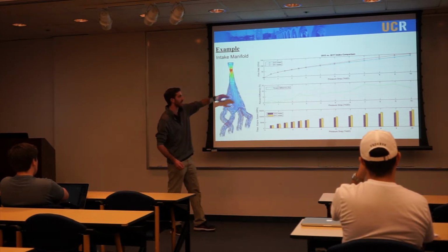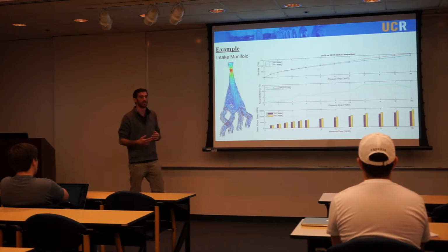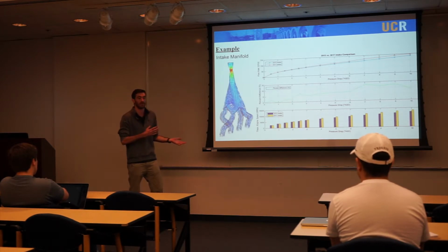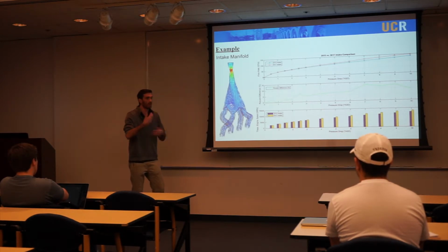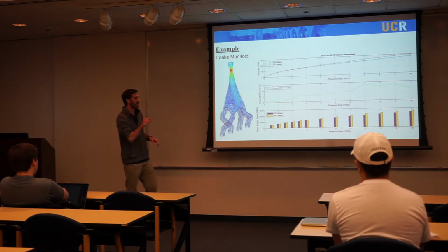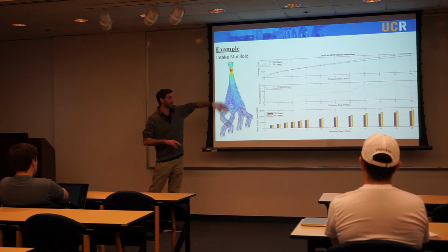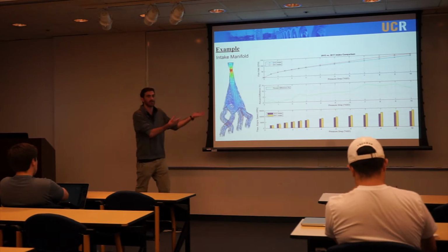So testing both the intakes and getting the pressure drop difference between them and seeing if you're improving was kind of a specification that I had early sophomore year: make sure the pressure drop is as low as possible, and then junior year it was make the pressure drop less than it was sophomore year. Always set that goal when you start designing. And it did come out well, and if you can do a physical test or a simulation, because I do have pretty much this exact same thing that I did through ANSYS, because ANSYS will tell you this info.